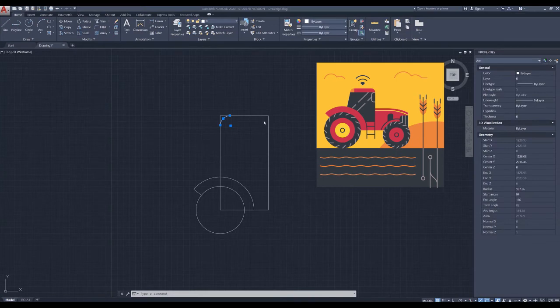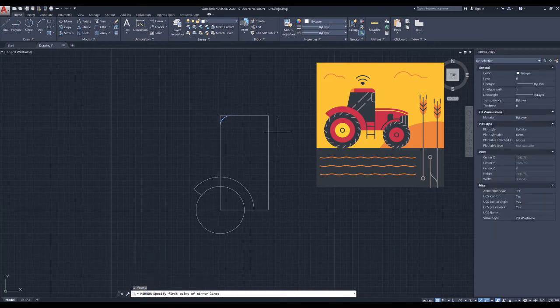Now I would like to have the arc on this side as well, but exactly the same. There's a really cool function that you can use, which is called mirror. So what you have to do is select the arc and in your command bar, type in mirror, and it usually comes up with only very few letters that you need to type in. Now you want to select what I'd like to call a midpoint, how you want it to mirror about, if that makes sense. So it's the mirror line.